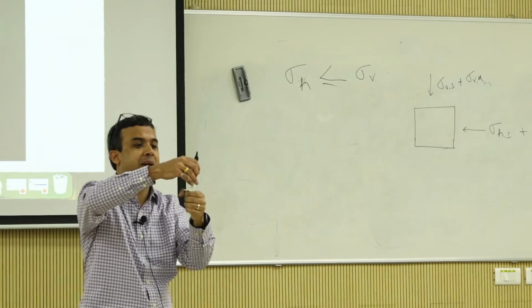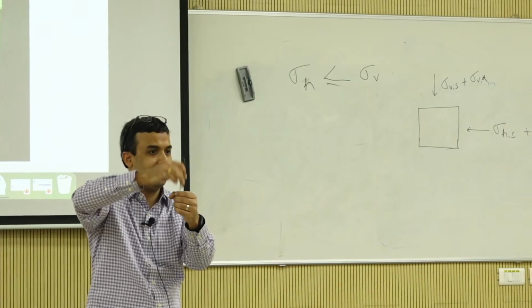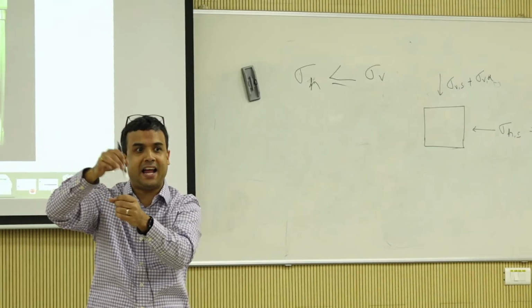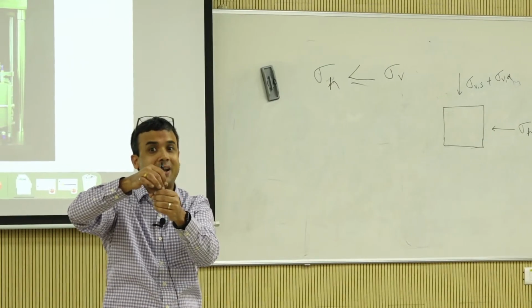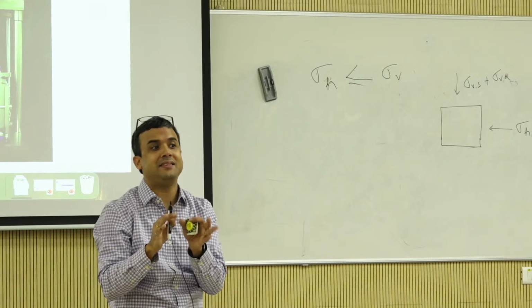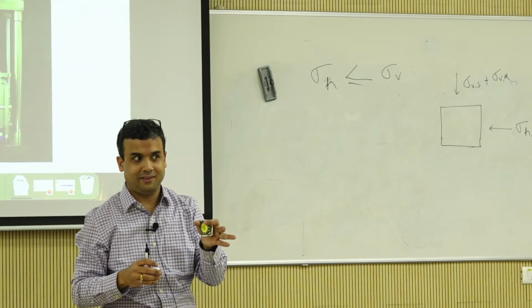And if I have a separate mechanism here, I can pulse it separately, can't I? Now you see that there is independent control over the lateral and the vertical, right? So when I do that, now I am getting one step beyond our conventional triaxial testing, right?